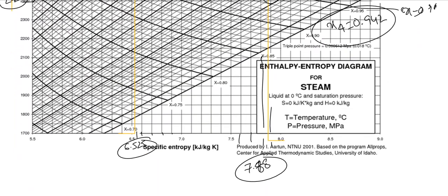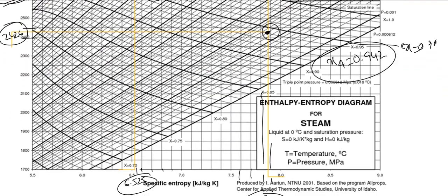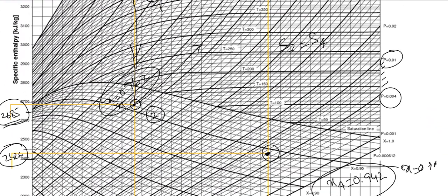That would be needed if you were solving it by the steam table, while in the Mollier diagram or HS diagram, you can find it directly. So let's rewind. At state 1 we have an enthalpy of 3324 and entropy of 6.525. At state 2 we have an enthalpy of 2685 and the same entropy of 6.525, and the value of x is 0.962.